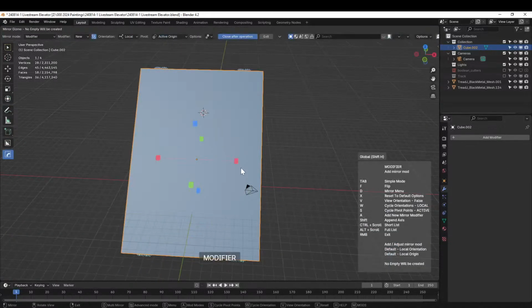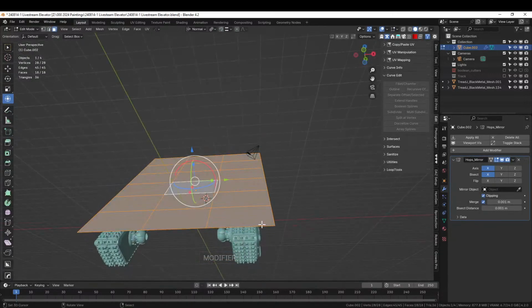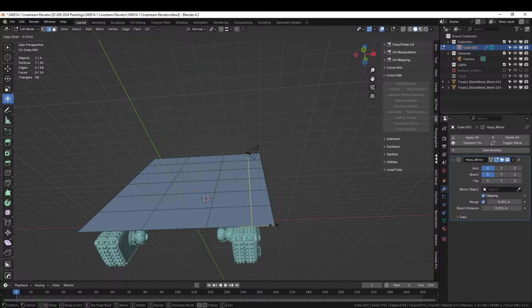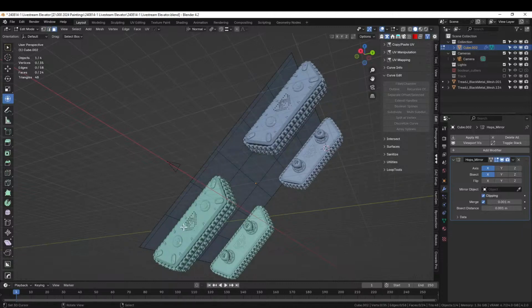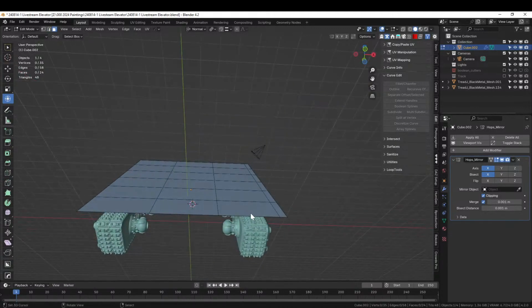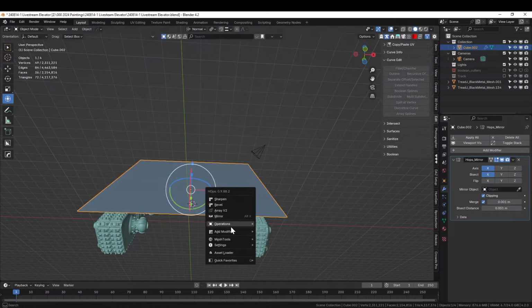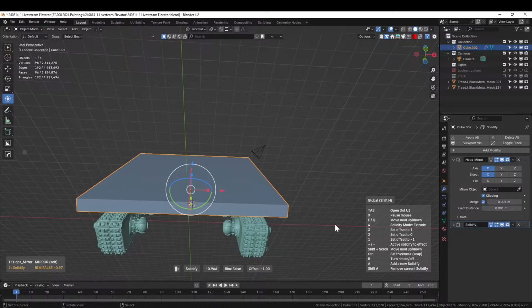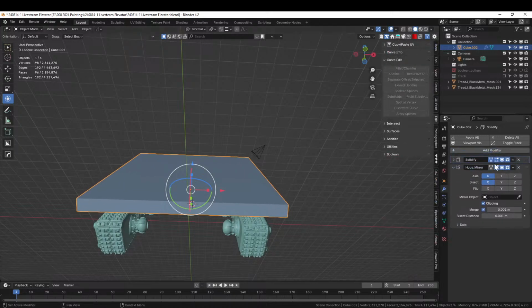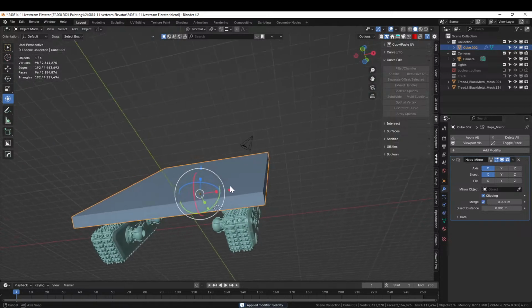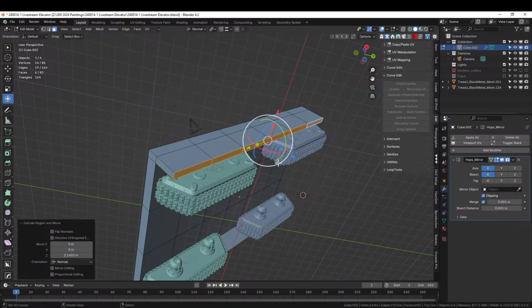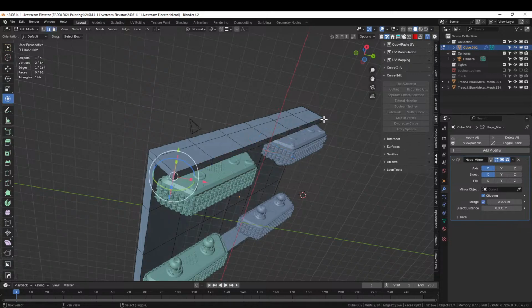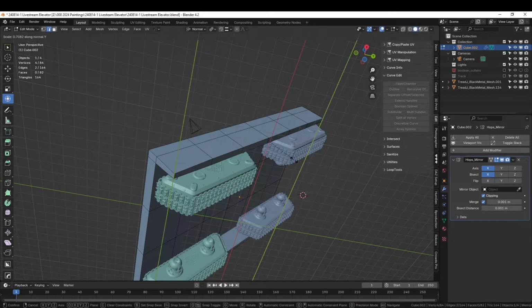And let's add a modifier. Mirror it. Control R, add an edge loop. There. And let's take that whole thing and Q, solidify it. Sure. And just apply it. I just wanted some geometry that was solid. Cool. Grab this, down, and this, S Y. Oh.